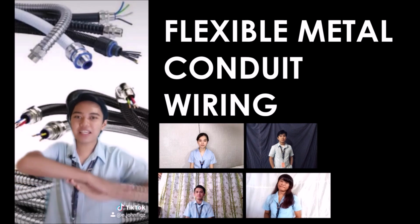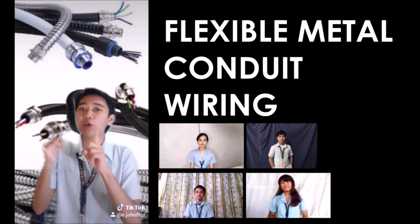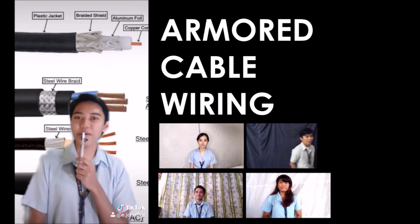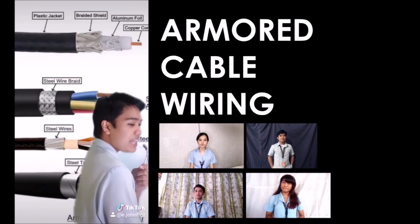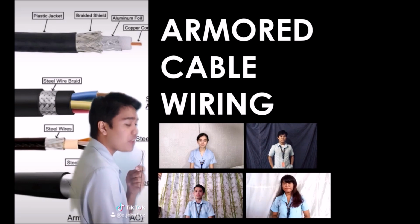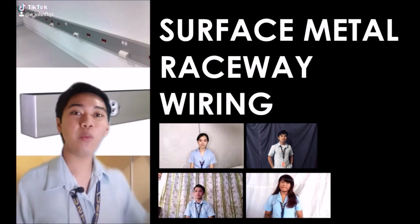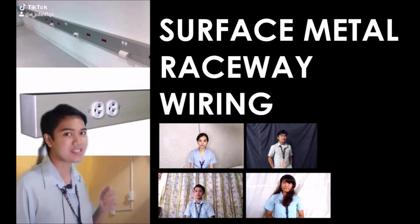Number 3. Flexible metal conduit wiring. Its installation is much easier and quicker, and it comes in lengths of 25 feet to 250 feet. Number 4. Armored cable wiring consists of rubber or thermoplastic covered wire protected from injury to a certain extent from dampness by 1 or 2 layers of flexible steel armor. Number 5. Surface metal raceway wiring. The wires are supported on a thin sheet steel casing and the insulation is exposed.